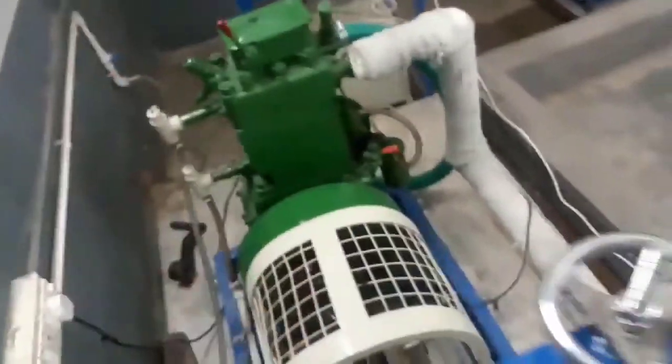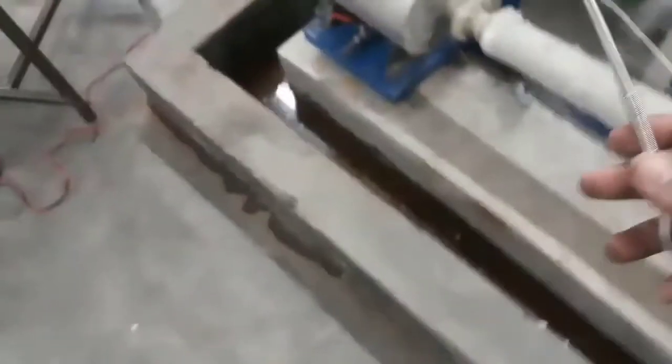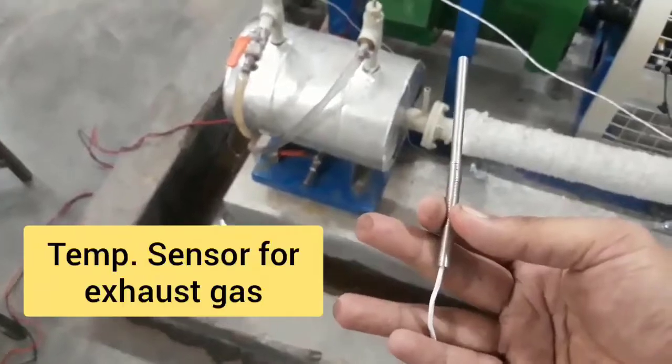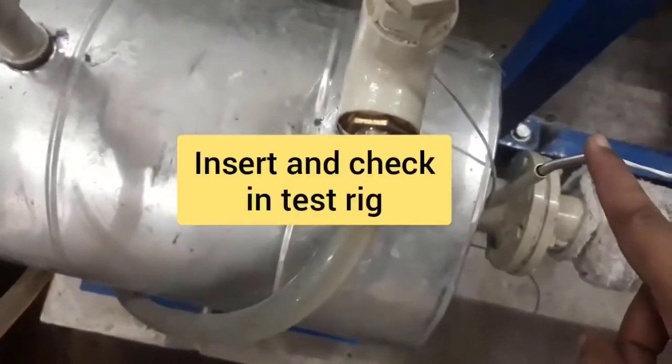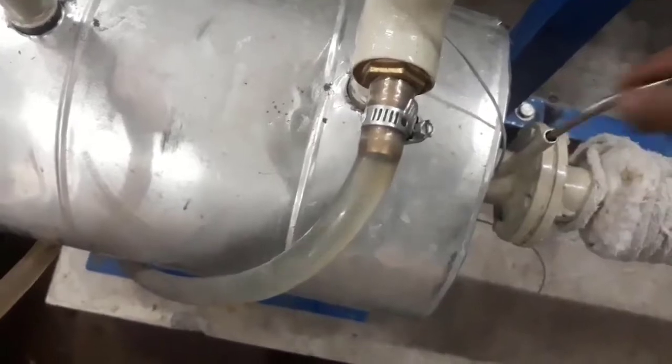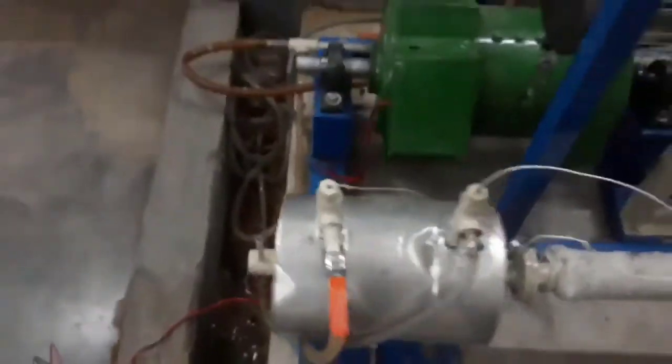So this is the whole engine, you can simply see. This was our experimental setup for understanding the Willans line method. Now we will start taking the calculation on this engine. And this is the temperature sensor for the gases. Also you can put it in an exhaust gas chamber. This is the PT100 sensor, which is useful for checking inside the test rig. In this manner we can check all the temperatures inside the engine and the test rig. This is the basic setup for the diesel engine, and we can perform the heat balance sheet method and the Willans line method experiment.